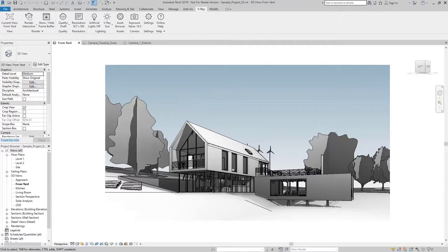However, I would like to focus your attention on the quality and resolution settings, as well as a few more things which are good to set up before we start rendering. In V-Ray for Revit, there are two render modes available: production and interactive. The difference is that in interactive, you can instantly see the changes you make to the rendering. Production is suitable for a final image when all the rest of the settings have been set up. During this webinar, we will run an interactive rendering so that we can track the changes we make.